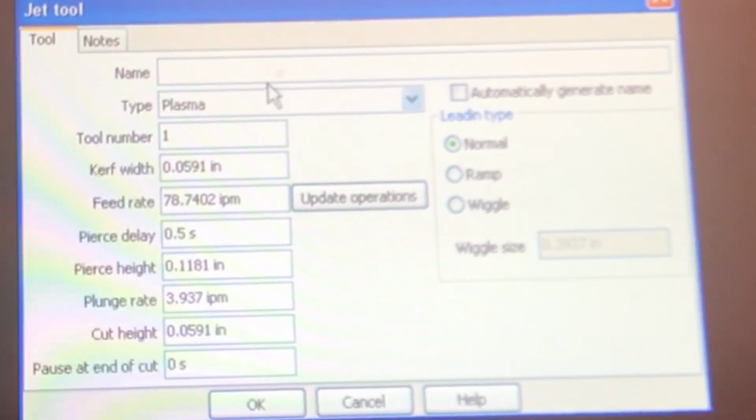We're just going to go with the basic settings off of memory, so the tool's not accurate. Just double check your manual or reference with your plasma cutter manufacturer to get these settings. The first way I like to label it is the amperage with which I'm trying to cut. Typically, I run a Hypertherm 65. We'll run lighter gauges at like 45 amps, and thicker gauges at 65 amps. One of the reasons we start off with this is just to notify us later on which nozzle to have in our Hypertherm plasma. So we'll start off with a 45 amp tip, and that's what we're telling ourselves.